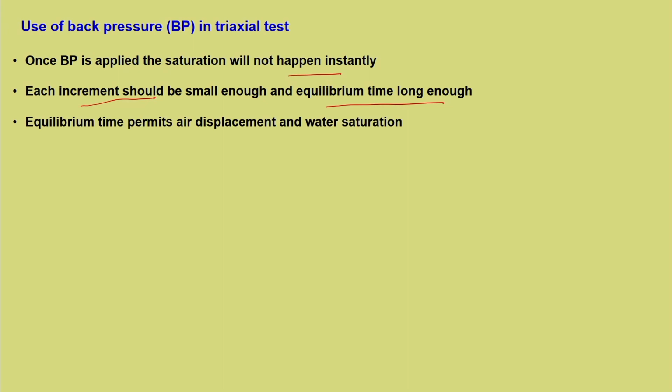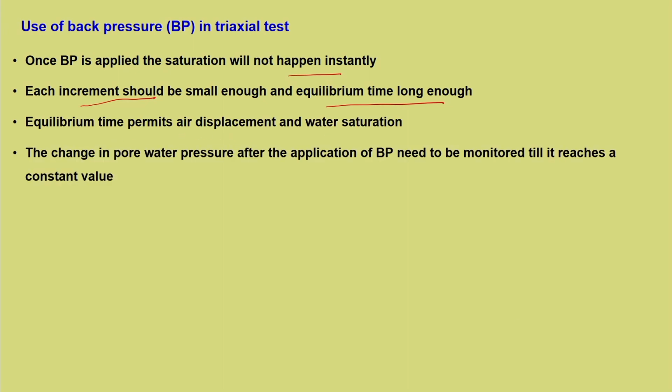You keep measuring the pore water pressure, it becomes constant. So, that indicates that the pore water pressure has almost equilibrated. If it is still rising, we have to wait for some time. So, this is what we need to keep in mind. Back pressure application is in small increments, and that small increment has to be kept for sufficient time, and that is known as the equilibrium time. So, equilibrium time permits air displacement and water saturation.